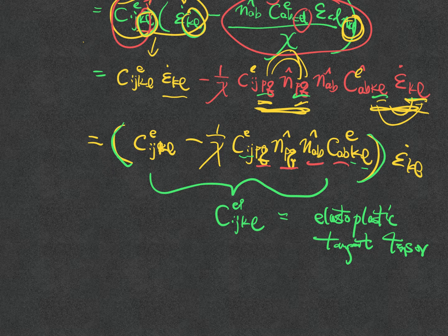So strain and stress have a mapping relationship, and you can control the stress from changing the strain. Now, if C^EP is singular or has a zero eigenvalue, then that means that you can change the strain a lot without changing any stress, which leads to the material being unstable. You see what I mean? If I can deform the material from here to here and I don't even change the stress, then I basically lost control of the material. I probably don't want to put it into a racing car, aircraft, or anything that has very important consequences.